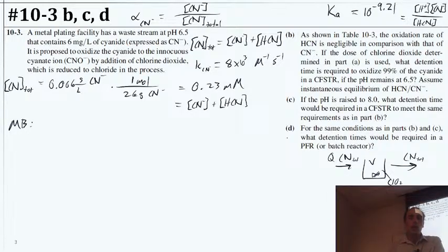Okay, the mass balance should be some function then where we have an effectively constant concentration of our chlorine dioxide. So this will look a lot like a first order decay where we have a steady state system and we have something going in, Q, and I'm going to do this on Cn, and I'm just going to put that in parentheses. That's total. Actually, for the moment, I'm just going to call it C. All right. We'll say C equals Cn total.